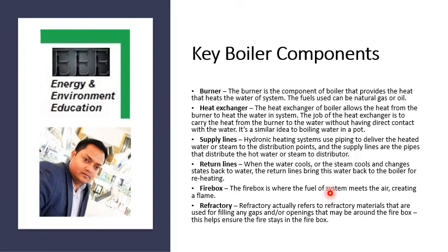The firebox is where the fuel of the system meets the air, creating the flame. And the refractory is also an important part. It refers to the refractory materials that are used for filling any gaps or openings that may be around the firebox. So basically this firebox is inside the boiler, friends, where the heating is taking place, and the refractory fills any leakage that may be happening there, because the boiler combustion area must be fully compact so that there is no heat loss. So this is a very important part.